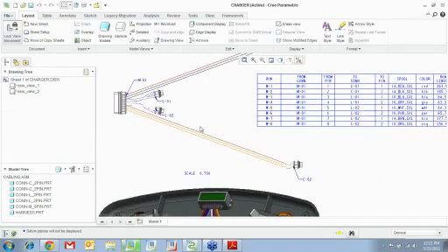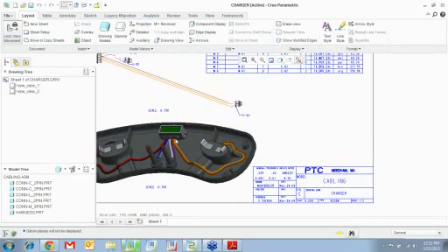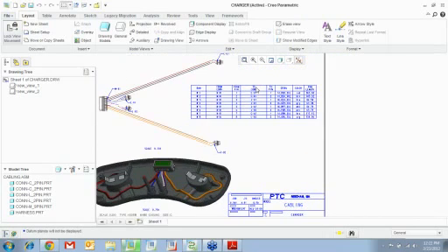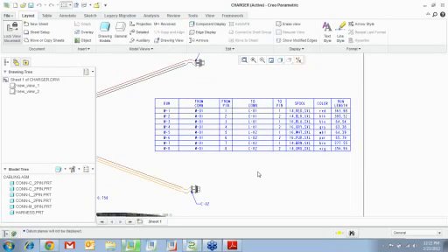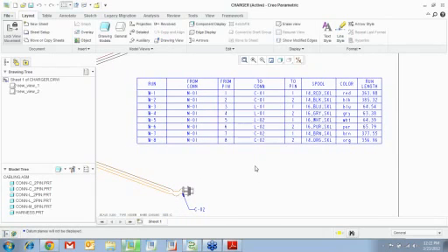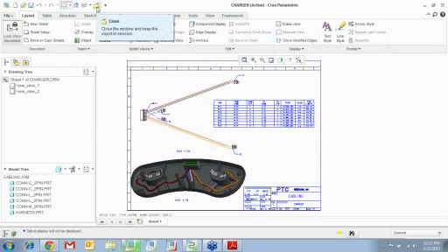You can see that you can actually create those nail board drawings where you stretch them out, right? You can create your 3D drawings. You can see that you have your from pin 1 to pin 1 spool, color, and length. All this information about each and every wire can be shown. This is read from the routed system designer into ProEngineer and from ProEngineer into drawing using the repeat region parameters. So this would be your cabling drawing that you might want to have.